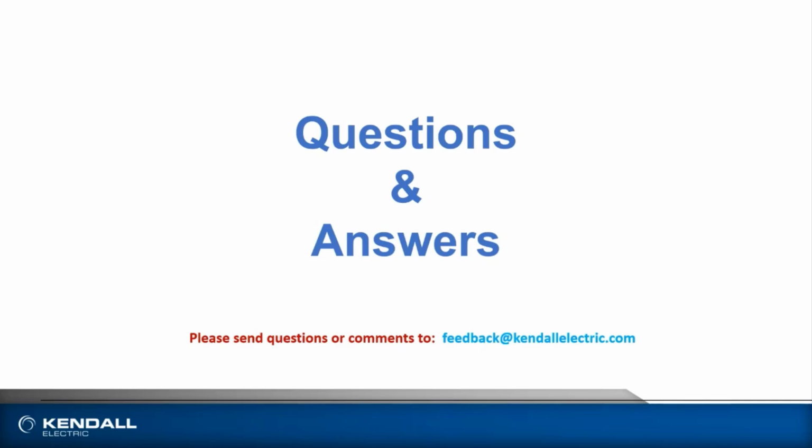Moving on, do the Micro 800s have online editing capability? Ryan, can you go ahead and answer that? If Ryan can't, I can address that one. Yeah, go ahead, Tim. Evidently, Ryan's got the same mute issue I had. You have the online editing capabilities with CCW software, which I mentioned. There's a no-charge version. There's also a developer version, which I want to say is about a $400 charge, that will give you the ability to do online editing. It has a different name, but the functionality is very similar to what you've utilized if you've done RSLogix 500 online programming with a MicroLogix 1400 or 1100.